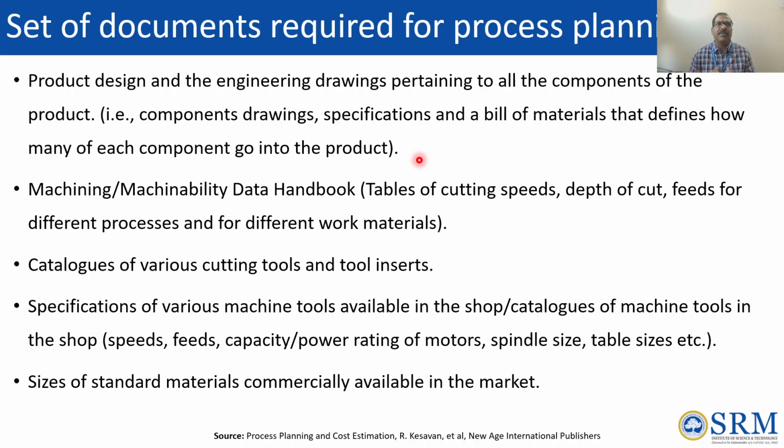Assuming we might have done some operation in our machine shop for rough turning, we have given a 0.5 mm depth of cut with the spindle rotation speed of 400 or 450 rpm. It depends on what kind of material we are using. Maybe we used mild steel. For the mild steel, we used 400 rpm with a 0.5 depth of cut. If we give 3 mm of depth of cut for the mild steel with the HSS tool, what will happen? Tool failure might happen, right?